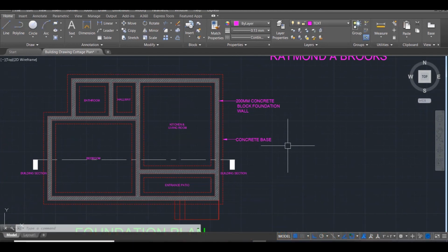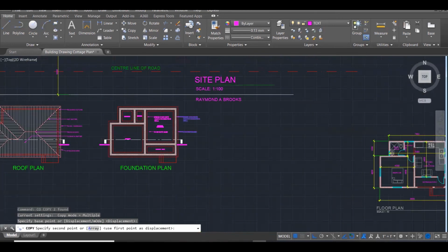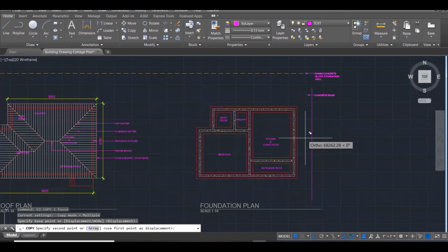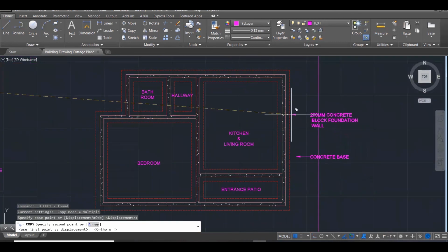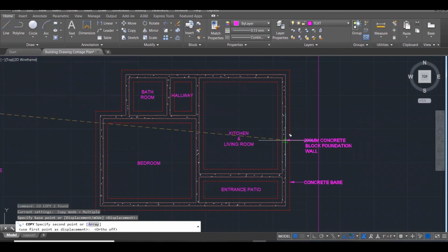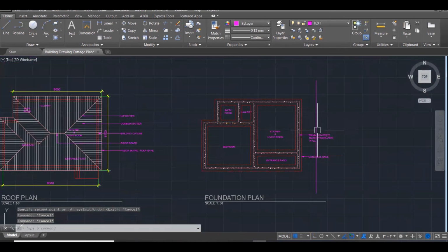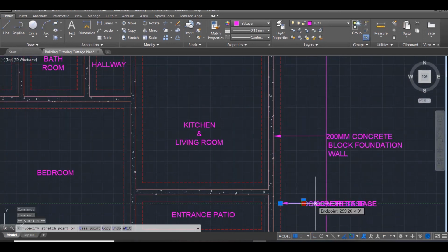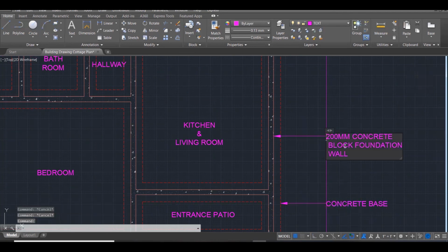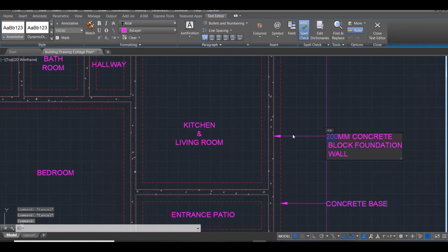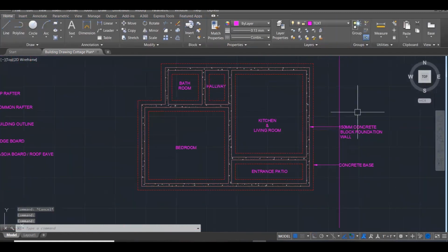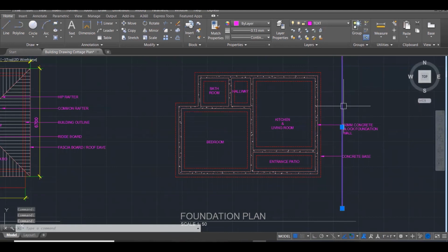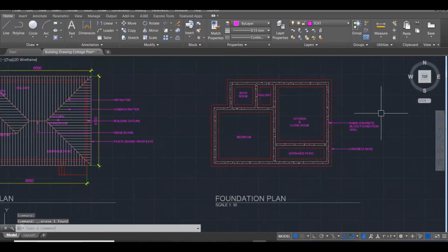And the next note shows the concrete base. Those are the two notes that we're going to be using. So I'm just going to grab them and copy them across rather than try to set up a margin at this stage, right? Turn off my F8 and let's see. So what do I have to look for before I just pull them back to here? Yep. Pull that back to there. Yep. And what size notes are these? 150, and change that to 150. So 150 is the size. That's cool. I take away my margin and I have all my notes in.